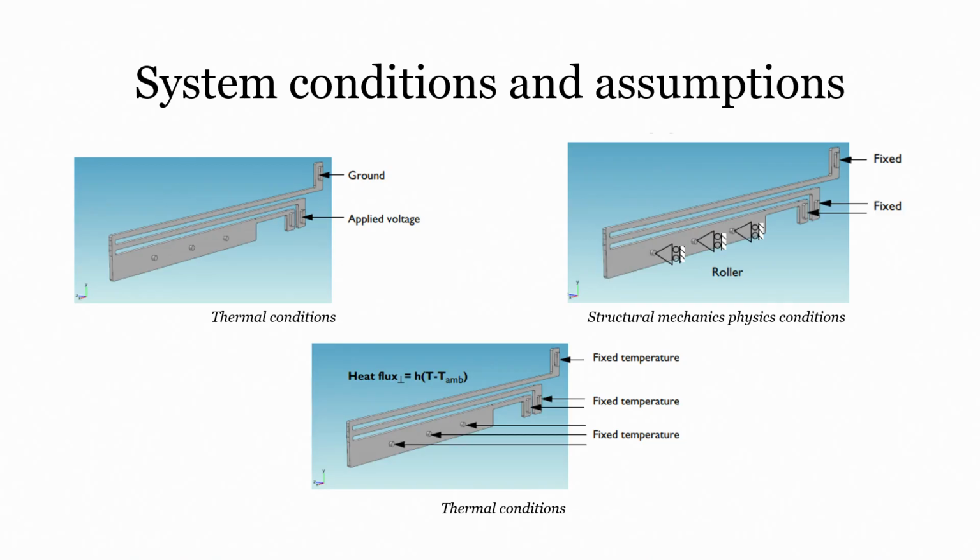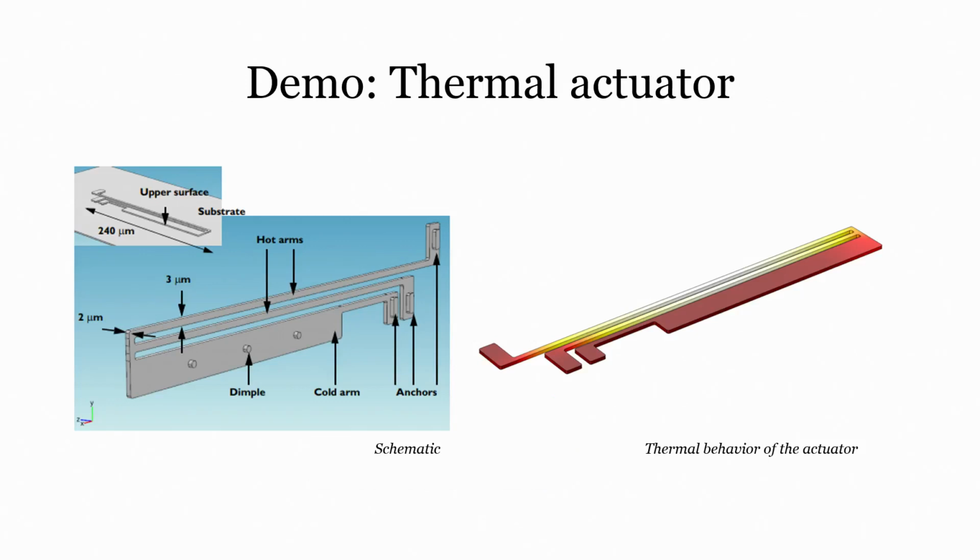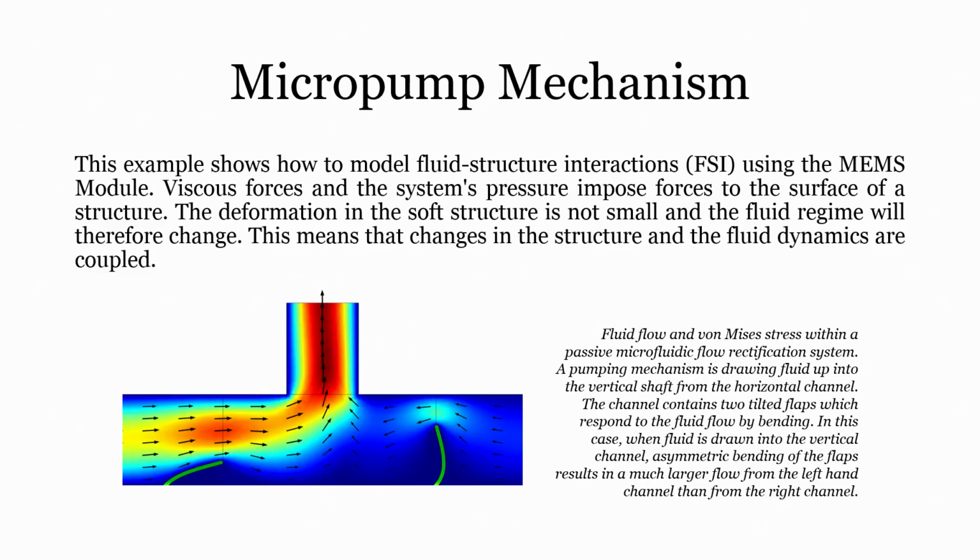In the same way, if you want to understand the design of microfluidics, you can also use COMSOL Multiphysics in detail, where you understand the fluid structure interaction when the fluid is flowing in a microfluidic channel. Alright, and in the same way we will understand how exactly the micropump mechanism would be used. In this particular example we will see how to model the fluid structure interaction, which is FSI, using the MEMS module.